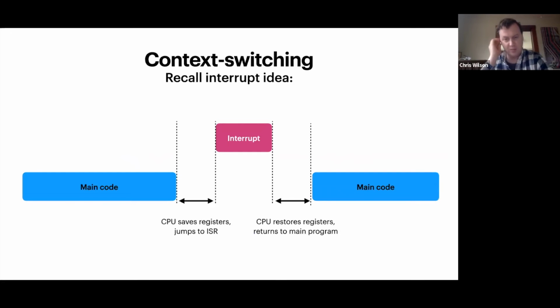Another topic that comes up once you start thinking about this ever-present idea of interrupts is context switching. A microcontroller is typically just a single core, unless there are ones now with multiple cores. It's like 1980s hardware: you'll be doing one thing and then an event happens, like a timer goes off, and the CPU will save all of your registers.